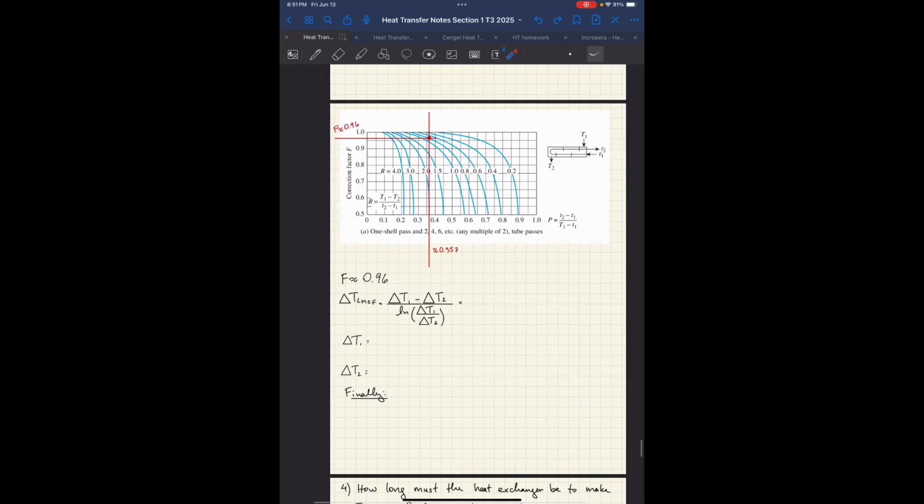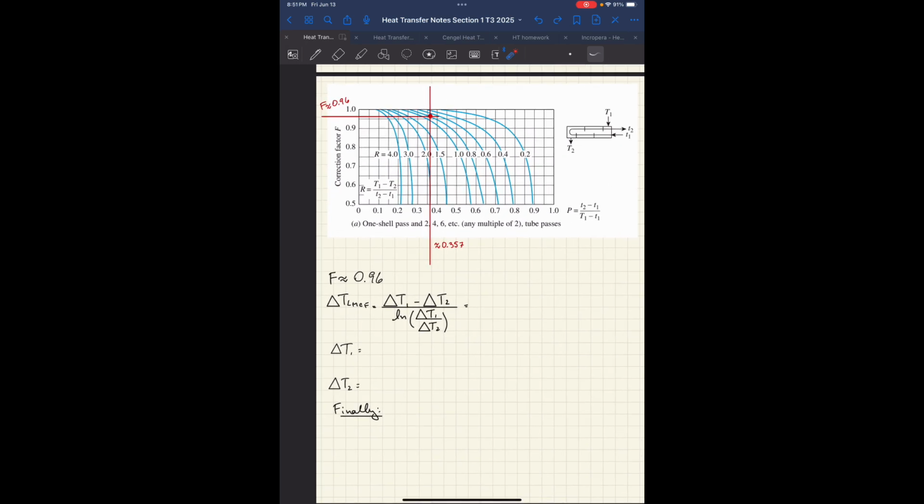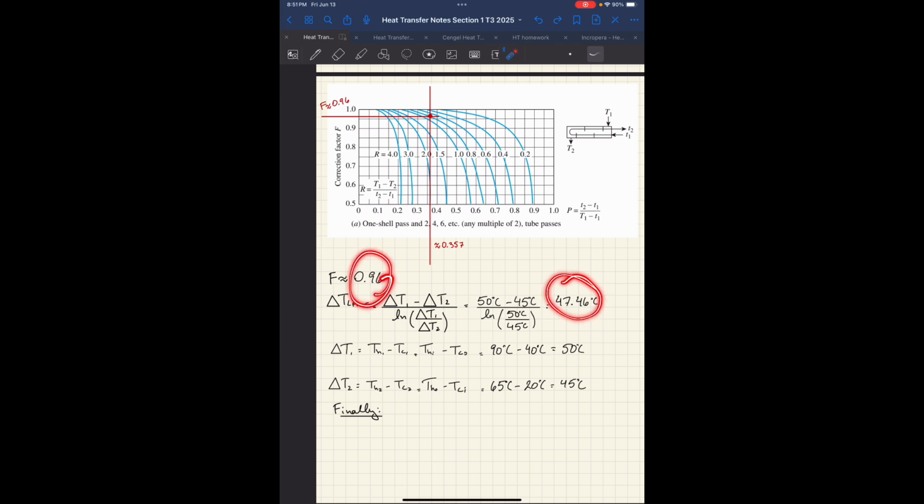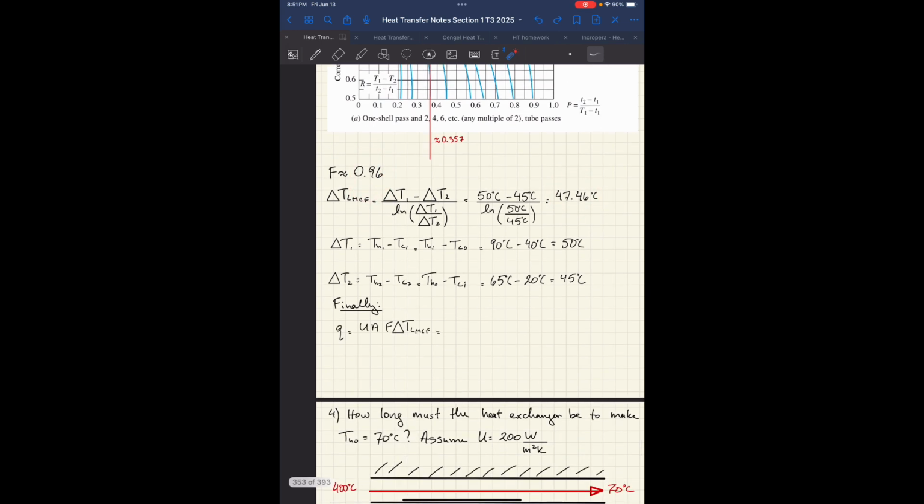So now you would calculate log mean temperature counterflow style. TH1 is THI, TC1 is TCO, right? You would work that out, do the same thing for delta T2. Calculate your log mean temperature as normal for counterflow, but then you have to modify this with your correction factor. And I did that in the final equation, UA times this, right? So F, the correction factor, is going to modify this number. So you get something like this at the end. So it's about 18.22 megawatts.